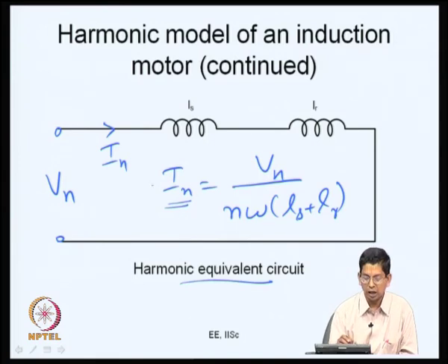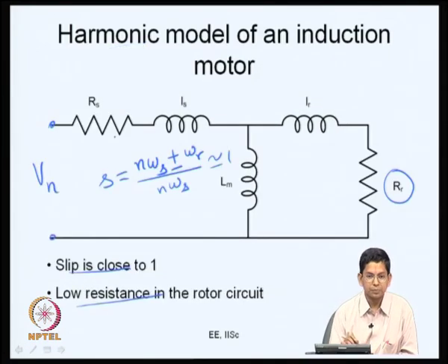So, now the current harmonic, what we see is, if you take the stator winding resistance like what is indicated here, what flows through the actual stator winding is not only the fundamental current, also several harmonics flow. So, when I n flows, I n squared R s, the nth harmonic current, also produces certain loss.